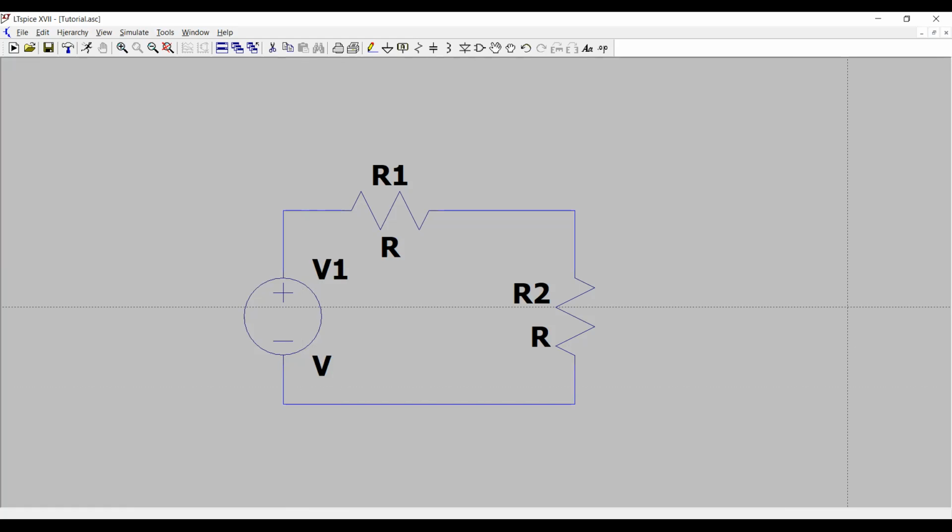Okay, so we have a complete circuit in front of us. I can press the escape key and get rid of the wire. If I wish to, for instance, delete something, I just simply need to either choose the scissor option that allows me to cut it from here. Another option is to click on that very component and then press the delete button on your laptop. It will give you the scissor option again, which is to cut it, and you'll have it figured out. So yeah.